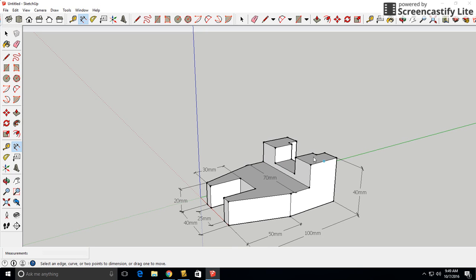All right, in the back, we've got a few more dimensions. Now, they've given us a broken dimension. They dimension this back corner 10, and then they dimension the rest of it for 20. I'm going to edit that. I'm going to start from the back corner and give an overall dimension of 30 out to the back. And then I'm going to add in a more detailed one on the inside of that. I can click on the inside corner, go from that endpoint to that point. It's going to give me a dimension of 10.